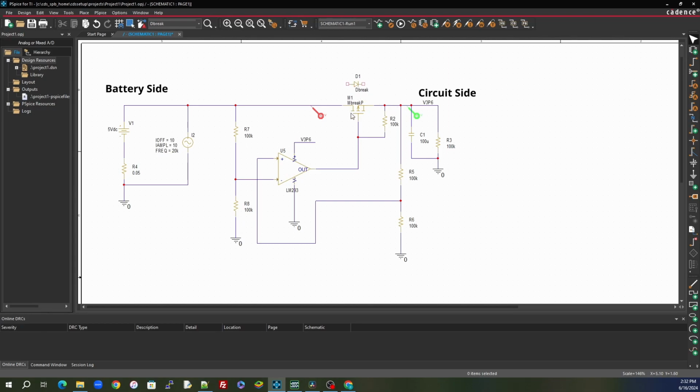Now if we look back, our N minus is tied to our battery, and our N plus is tied to our output. With the open drain comparator, according to the data sheet, when N minus is greater than N plus, the open drain gets shorted to ground. That's what's happening right now. I've got 5 volts here, and through the body diode, 4 volts over there.